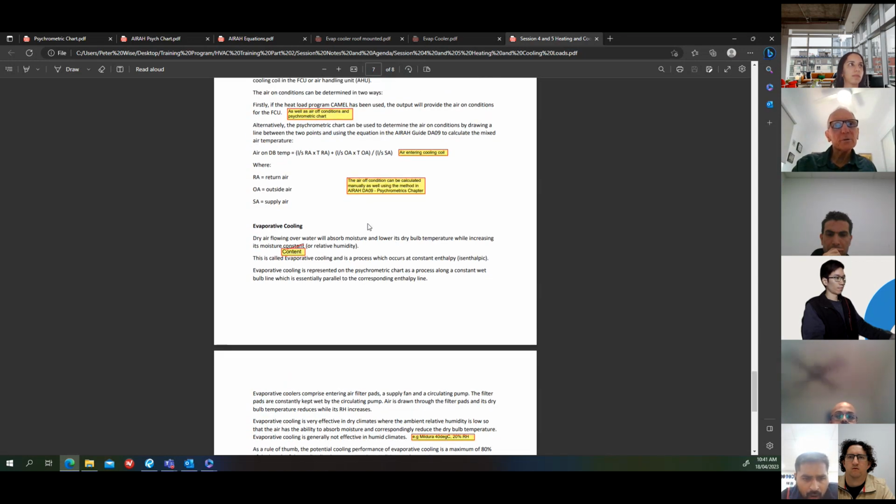All right, let's move on to evaporative cooling. I put this in because it's a process that we do use occasionally, and it's probably more relevant to industrial projects rather than the commercial office buildings. Sometimes it's used for make-up air for kitchen systems, kitchen exhaust systems. So you can use an evaporative cooler to supply air for the makeup for a kitchen hood, so you get some cooling.